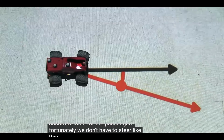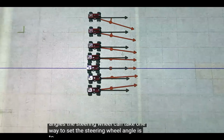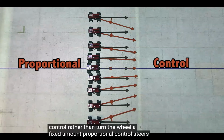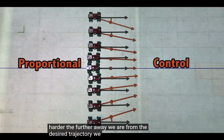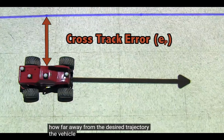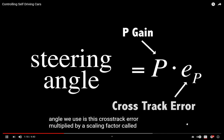Fortunately, we don't have to steer like this in a car, since there is a range of angles the steering wheel can take. One way to set the steering wheel angle is to use what is called proportional control. Rather than turn the wheel a fixed amount, proportional control steers harder the further away we are from the desired trajectory. We take a measurement called the cross-track error to define how far away from the desired trajectory the vehicle is. Therefore, the steering angle we use is this cross-track error multiplied by a scaling factor called the proportional gain.